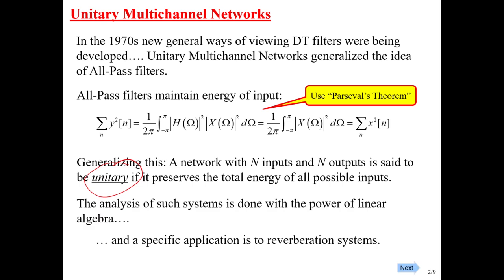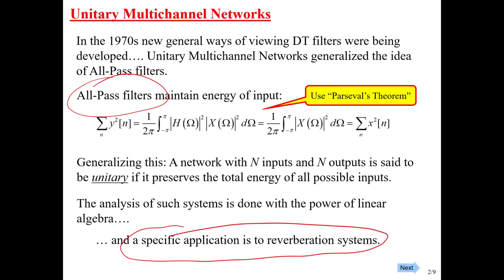This was developed in general, and then people recognized that once people started using all-pass filters to emulate reverbs, we can take this general idea of a unitary multi-channel network and apply it to reverb. That's where this feedback delay network approach comes from.